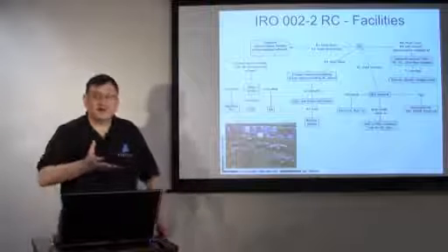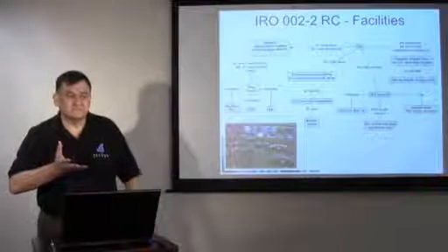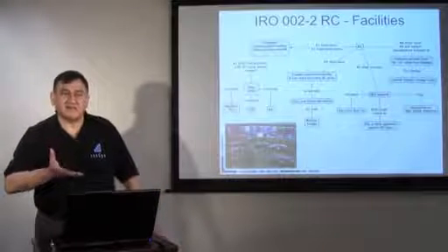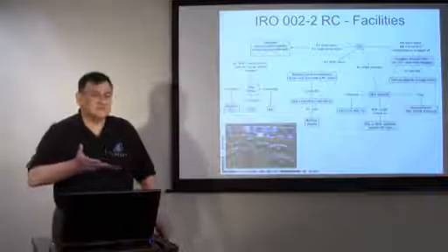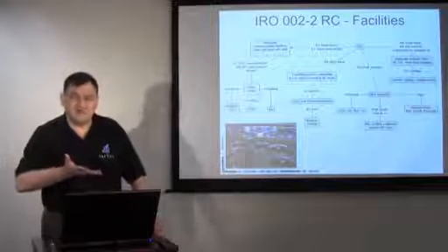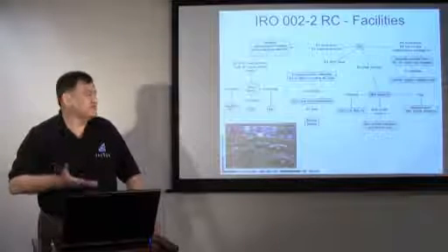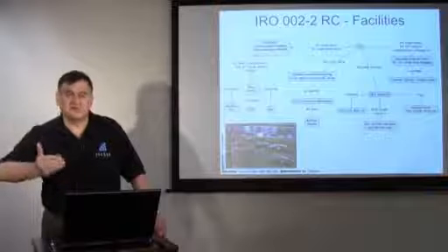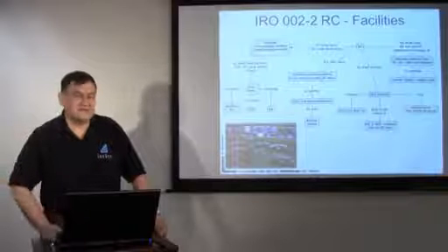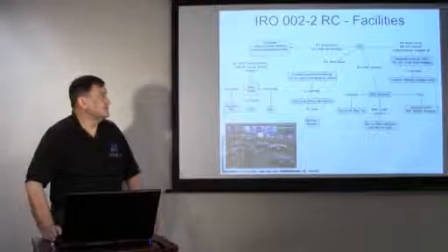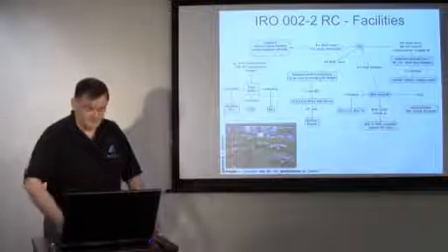And again, we talked about just one data entry error. Getting the reactances off by a factor of 10 can be enough to cause those programs to diverge. So it's really important that those models be accurately calibrated and tested so that we have reliable results.